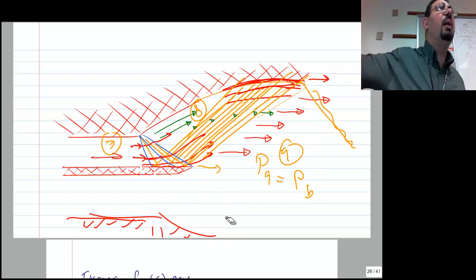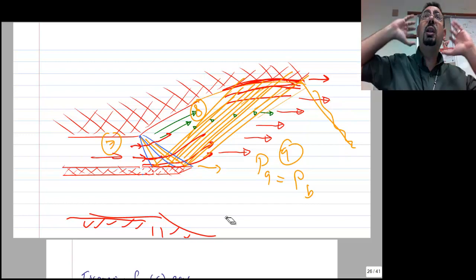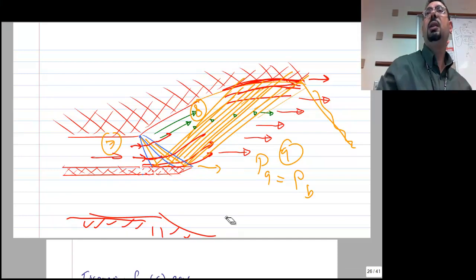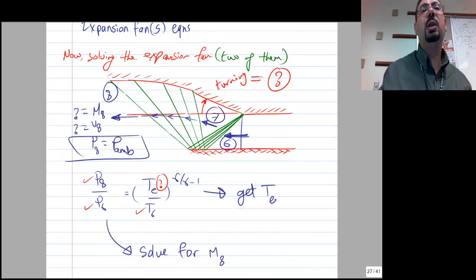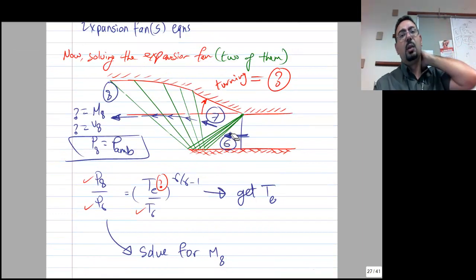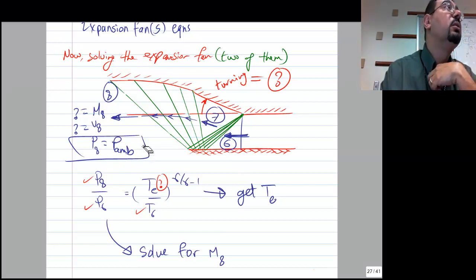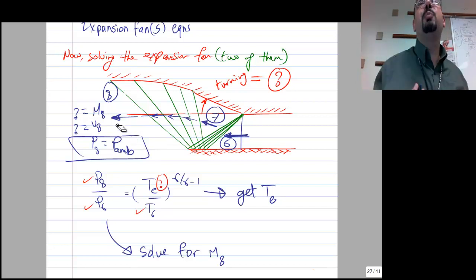And what's the big deal? What will happen outside? Well, the flow basically starts taking a direction, and you don't get a proper jet. If you want to send it out and get full thrust, you don't want to send it with an angle. You want to get it straight out. So that's what I'm trying to explain here, that the pressure over here eventually needs to be equal to P ambient. Otherwise you have an under-expanded nozzle or an over-expanded nozzle. You want to finish at P ambient.